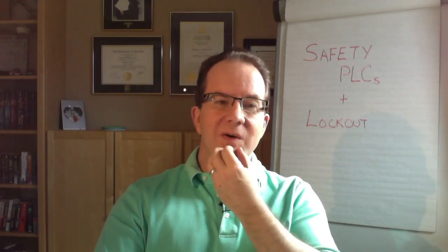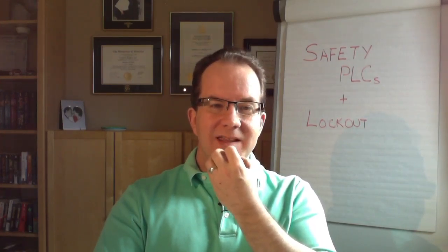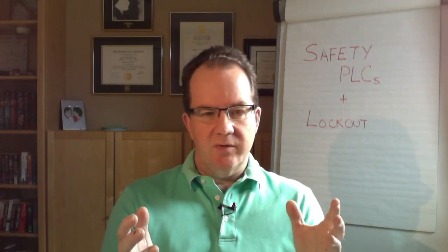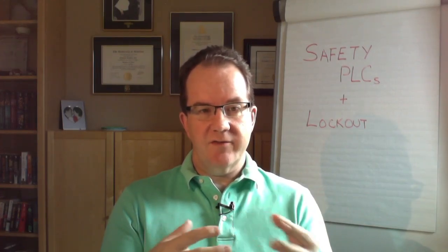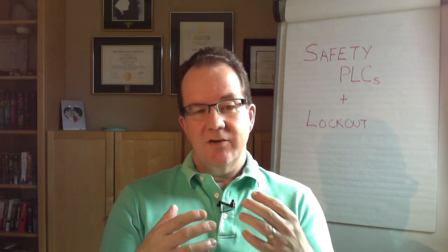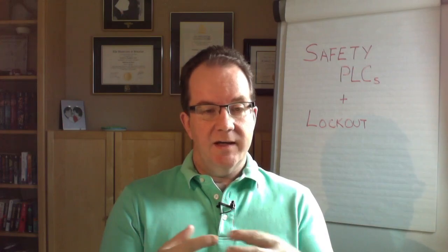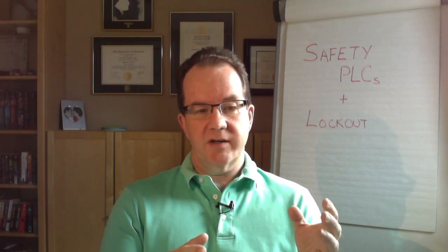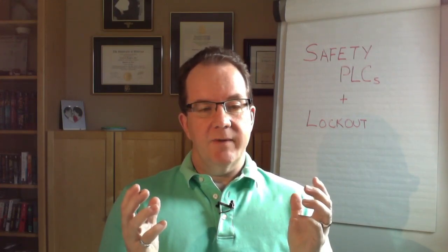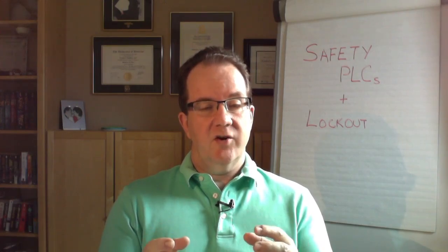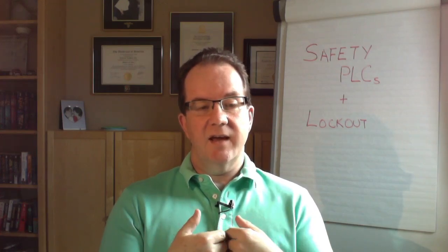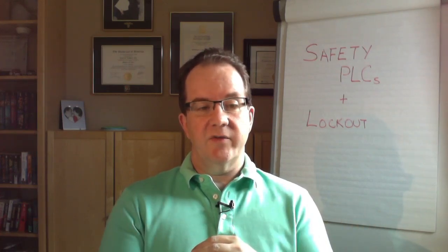Okay. So I think really we've answered the question using reliability. And since power remains available, if you're trying to use the PLC drive combination, then you're in a situation where if something goes wrong, and it is quite possible, especially when we're talking about systems that are using category 3 architectures, it's quite possible to have undetected dangerous failures that the diagnostics in the system can't diagnose, can't detect, and it's still possible to lose the safety function.